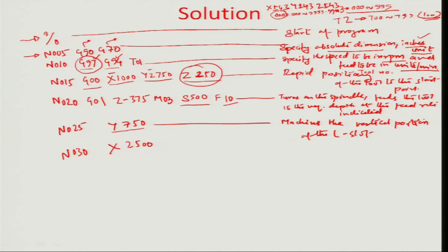So automatically the axis motion command indicates that the tool has to feed forward in the x direction by about 1.5 inches, because earlier you had defined the position as 1.000 inches and now you are defining it as x 2.500 inches.